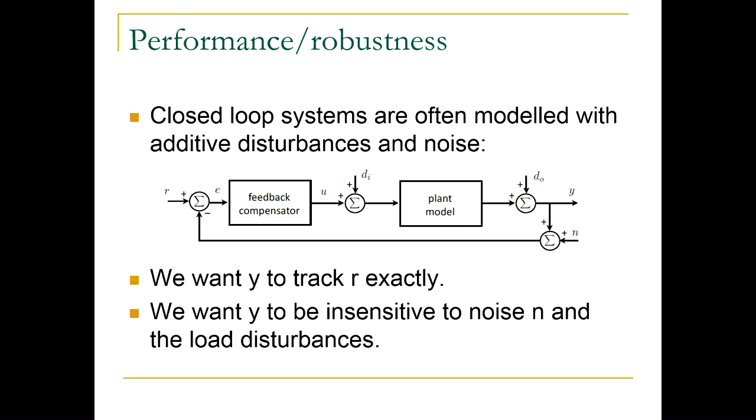But if I don't do that, if I just say, okay, I'm now dealing with this thing which is just R minus N. I want to follow R, but don't want to think about N. You are hitting the true issue, the frequency. Noise is high frequency typically, whereas R is typically low frequency. If you wanted to follow R, which is of the same frequencies as N, good luck to you.